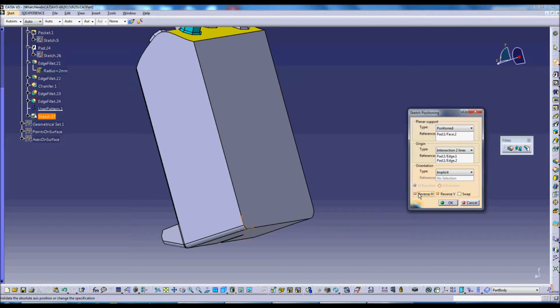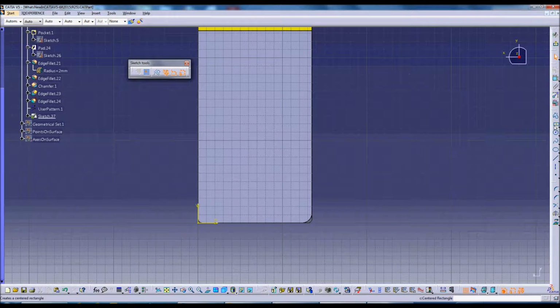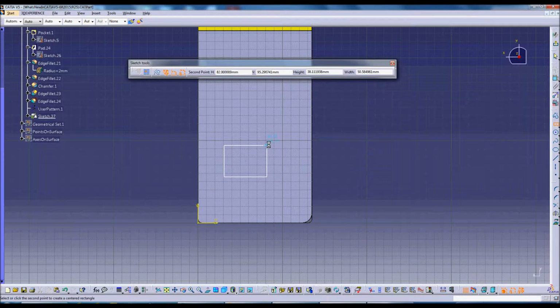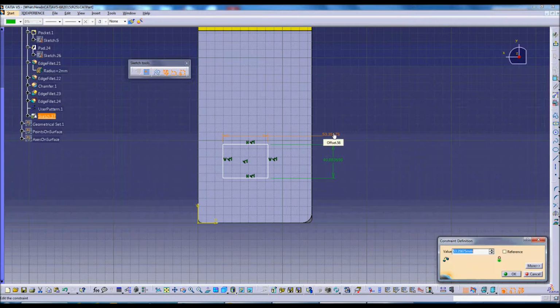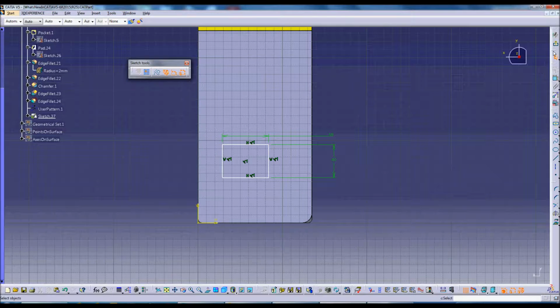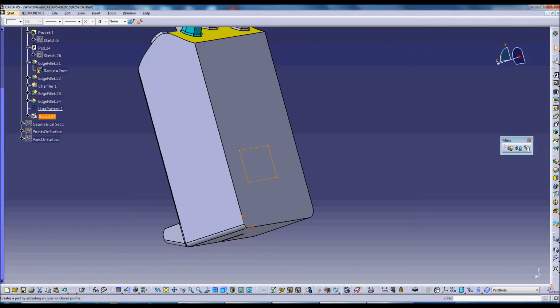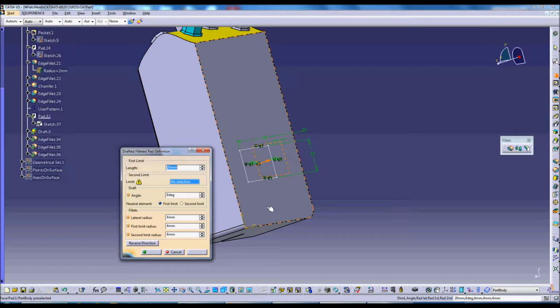So we're going into a sketch with the automatic dimension turned on in the sketch tools. So now when we create a rectangle, for instance, and other shapes as well, the length and the width are automatically positioned as dimensions. You just double click on them and change them on the run. So this adds to the circles and corners and things that have already been automatically dimensioned.